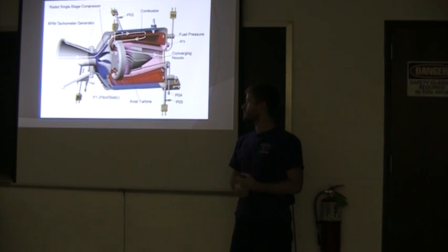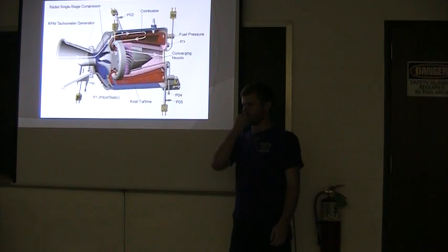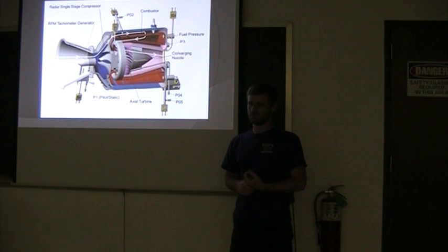I guess it depends what you need it for. I think, well, you probably do need a turbine to expand the gas more. Right. If you go back to your Brayton cycle, the cycle that you showed, you can answer from there. Why do you have a turbine? What's the function of the turbine? It's to decrease the pressure and temperature. When you have a really low pressure at the nozzle? Yeah. You have high velocity at the nozzle. So you have to have a low pressure. So pressure is comparatively lower.